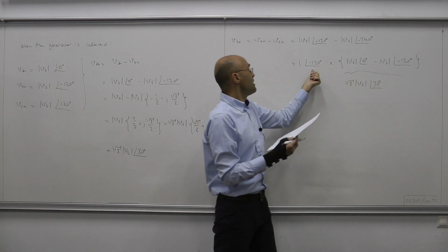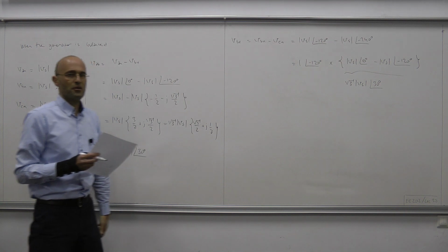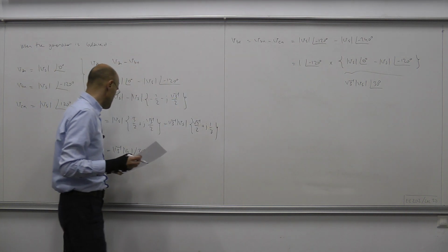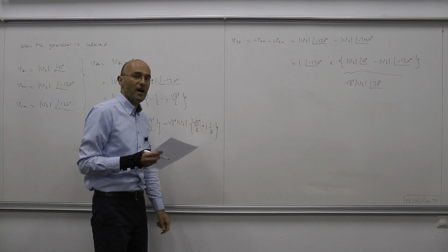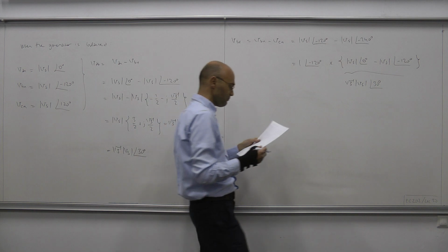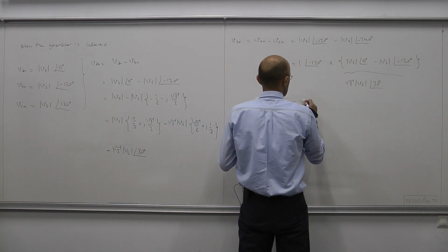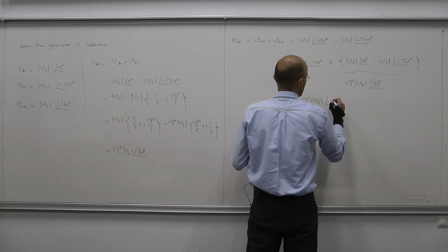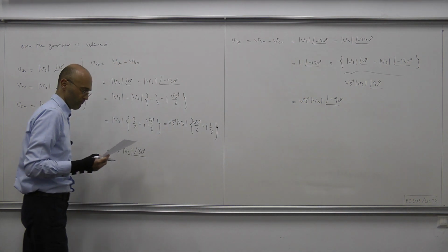To 30 we add minus 120 degrees, therefore it produces minus 90 degrees as phase. So VBC has the same magnitude and its phase is minus 90 degrees. So that equals square root of 3 Vs and the phase is minus 90 degrees.